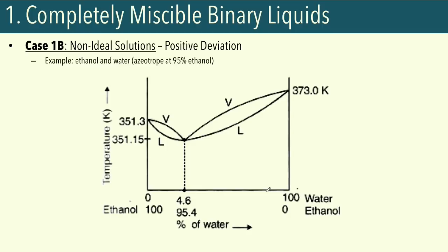You can see here that if we have our 30% ethanol and then we do a distillation, the distillate is going to have a corresponding maximum composition of this over here. So we're approaching a richer ethanol composition, and if you do this again and again, ultimately we end up at the azeotropic composition. If you try to distill an azeotropic mixture, what's going to happen is that you have a liquid that is 95% ethanol, and we'll find that the composition of the vapor is actually going to be the same.